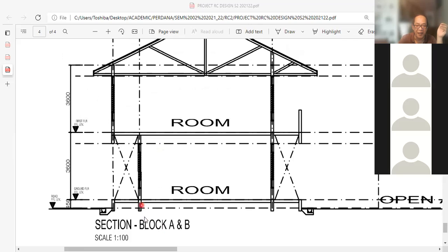Okay, so we've looked at two things just now. One is the ground slab. We've come to a conclusion. It has to be designed as a suspended ground slab. Number two is that the perimeter ground beams, all the perimeter ground beams, have to be deeper than 450 mm. Okay, maybe 600, maybe 650 mm. That would be a reasonable dimension, so that it covers the whole depth of this 450, the difference between the ground level and the ground slab level, right?